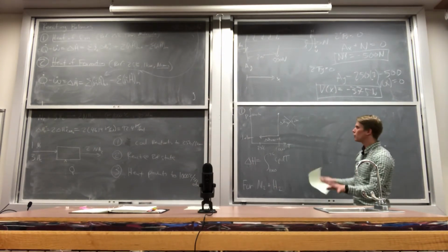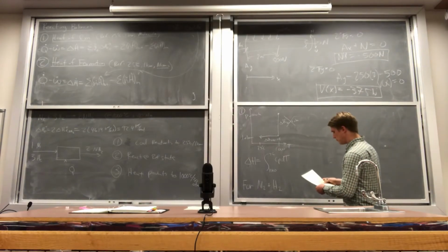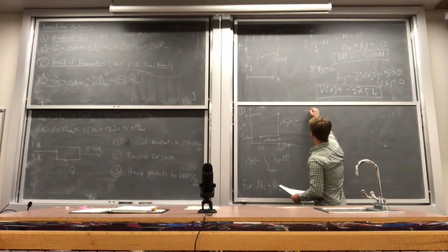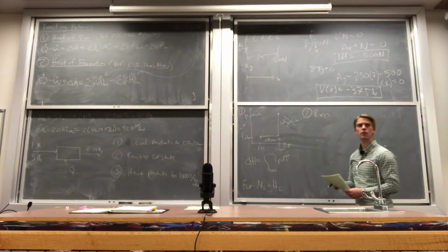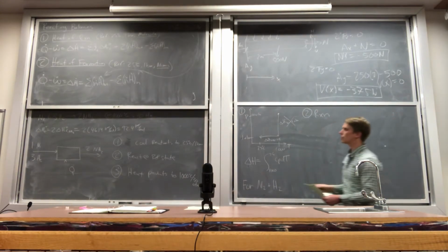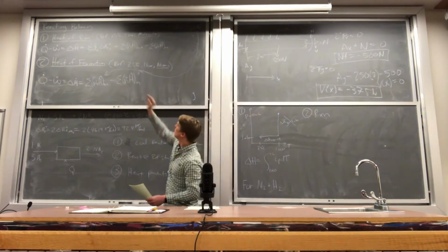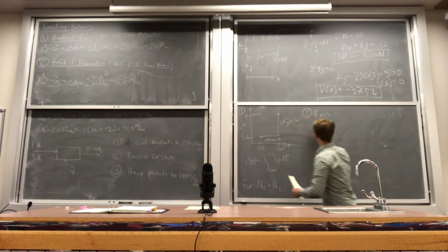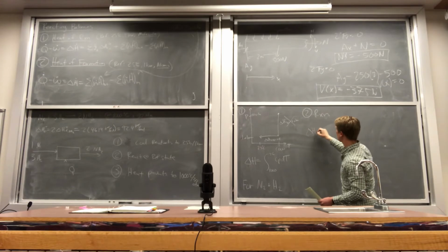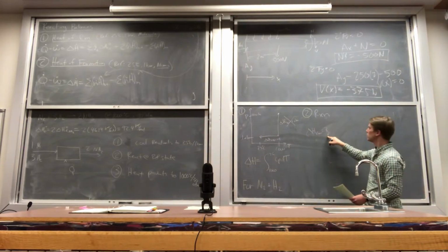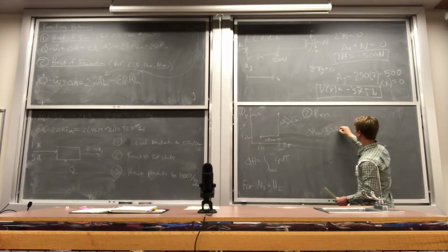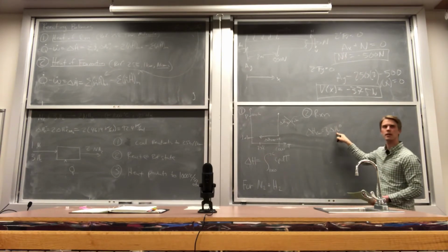Right, so I just want everyone to get the flow of what's going on. Step 2, the reaction. In this case, it's relatively straightforward. It's just direct application of that formula there. So the delta H for the reaction step would be the extent of reaction times the heat of reaction.